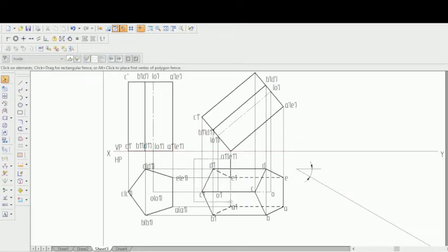While selecting, it is very important that the center lines also get selected. You can see here not all the lines are selected, the center lines are ignored. So go to the split option and split these lines, especially the center lines. Center lines, as I told, are very, very important. Let's split so that you will get the center.